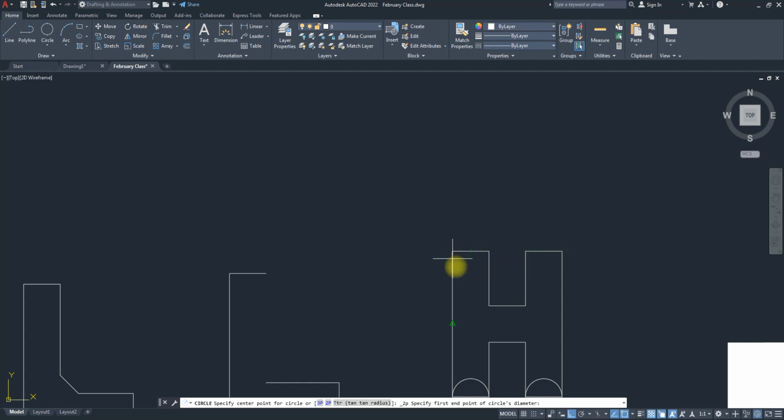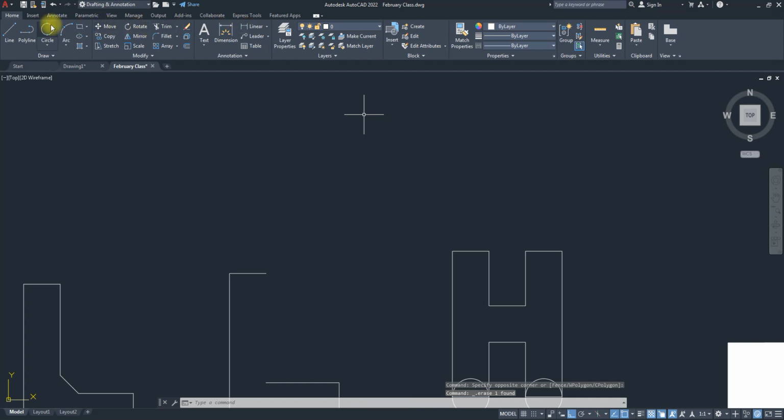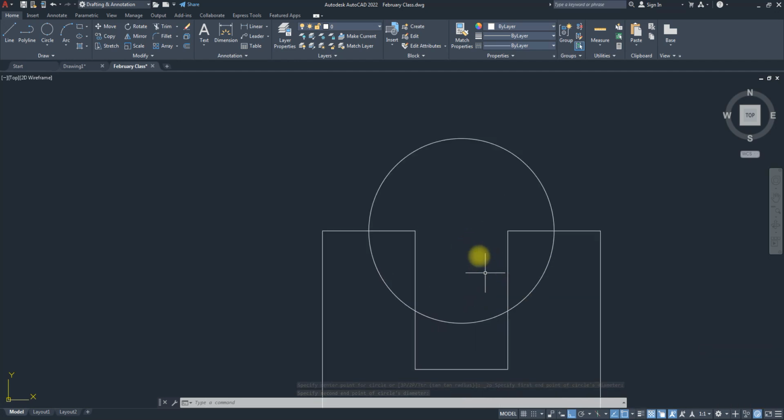So you can actually utilize that. When you have that, you don't need to get exactly to the midpoint. Once you come to the object and you click, it automatically snaps to that midpoint. Come to this place and you click, it snaps to that midpoint. You notice this one snaps. So this is not the midpoint, I think because I missed that, so let's come here. If I come here, it snaps. Can you see? Come here, once I click, it snaps. Do you see that? So you can utilize these object snap points to your advantage also.